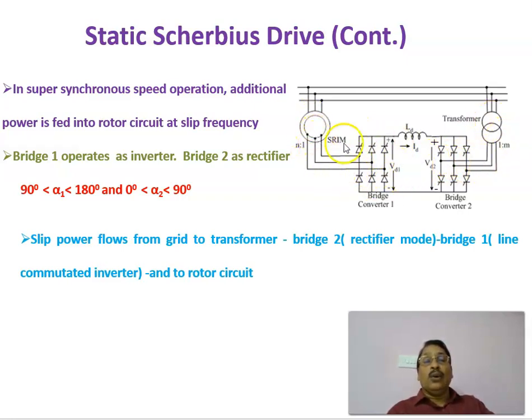Therefore, by controlling the power flow from the grid into the rotor, you can control the speed of the slip ring induction motor above synchronous speed. That is the application of the static Scherbius drive system in the supersynchronous range.